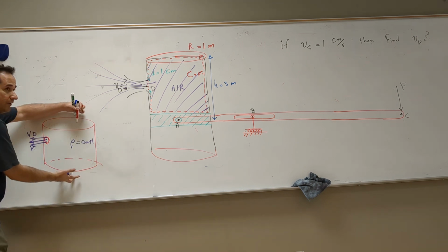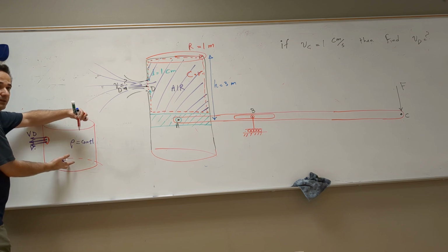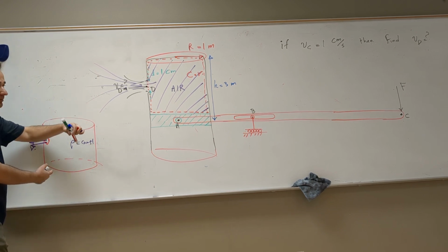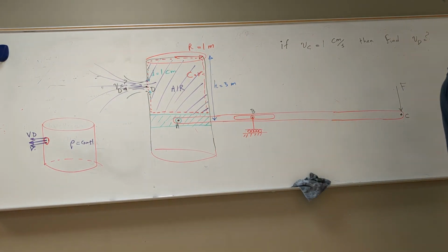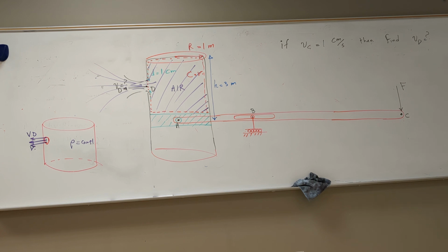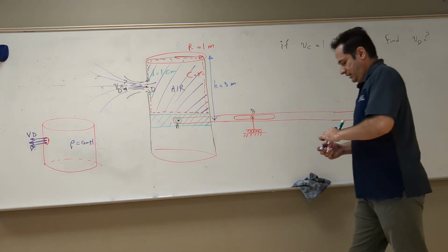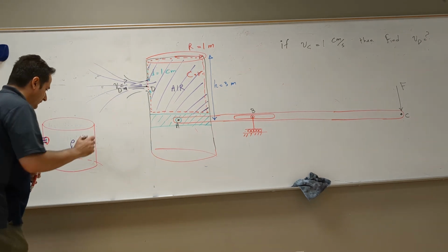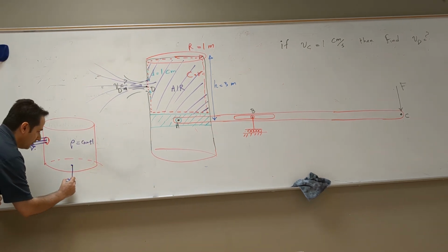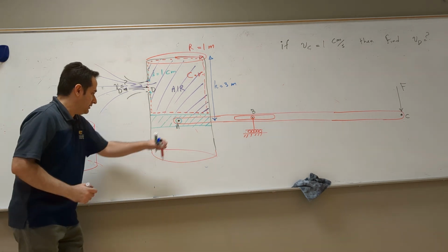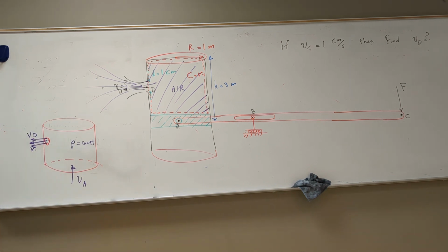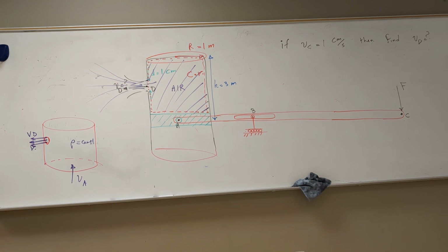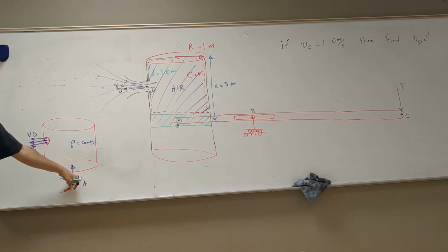But look, my volume is compressing, is expanding. Why? Because this piston, at this point I don't see it, but later on, versus time, is expanding. What does it mean? The mass per volume changes. Well, that's exactly what it means. So if I find the velocity of this point, V at A, if I know how much my dA is, I know how much compression I have. And then by applying the continuity equation, I can find a relation between that and this.